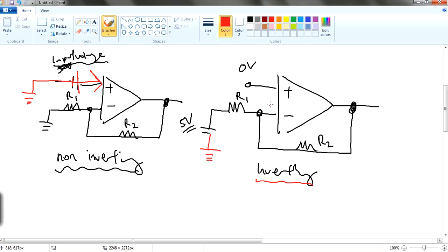And then the governing equation for non-inverting is R2 over R1 plus 1 equals to, they call it AV. Okay, so it's not like AV, but it's like gain. So this is gain. So you amplify the gain. Let's say you have a difference in voltage over here. You multiply by this gain, you can actually have an output voltage. You can calculate it already.